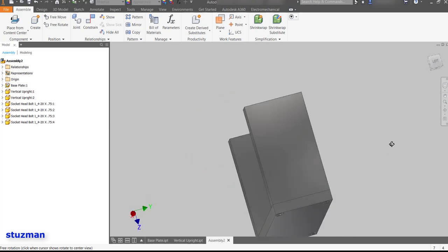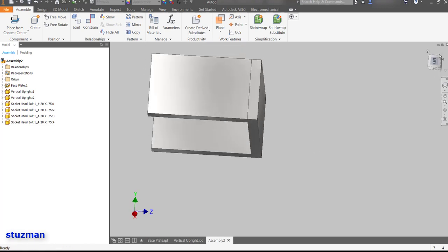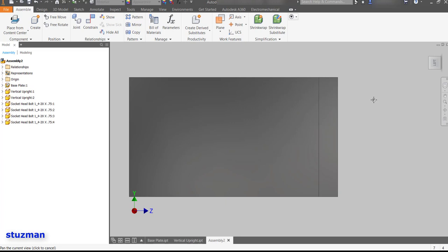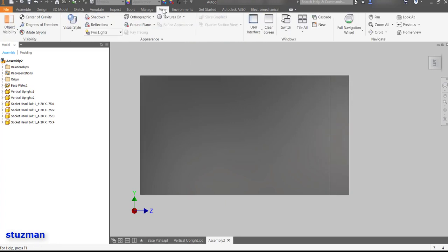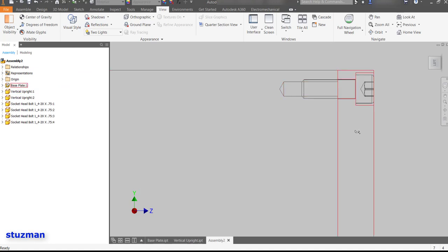now let's say I'm looking at these bolts, and I just want to make sure everything looks good. So I'm right here, I'm looking at it, and I want to look at these bolts in here. So let's change our view. We're going to go to view, and I'm going to come down to wireframe. So you can see there's the end of my bolt. This is the end of my tap toe. So if I wanted to, I could get a little bit longer bolt, say probably 1/8 of an inch.